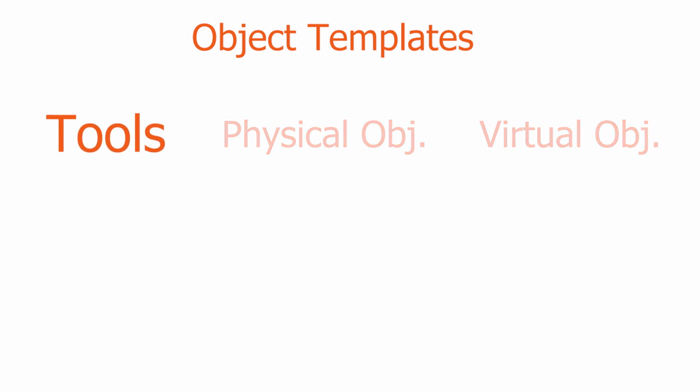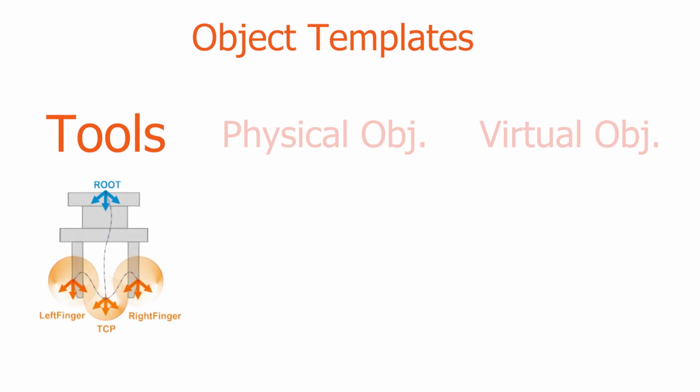Tools implement the IMovable interface and can be attached to the end of the robot or the flange of the robot. An example of a tool could be a gripper that has been mounted on the flange of the robot. Additionally, tools can be safety rated, in which you can add spheres around the tool and add the tool into the safety configurations to be monitored.